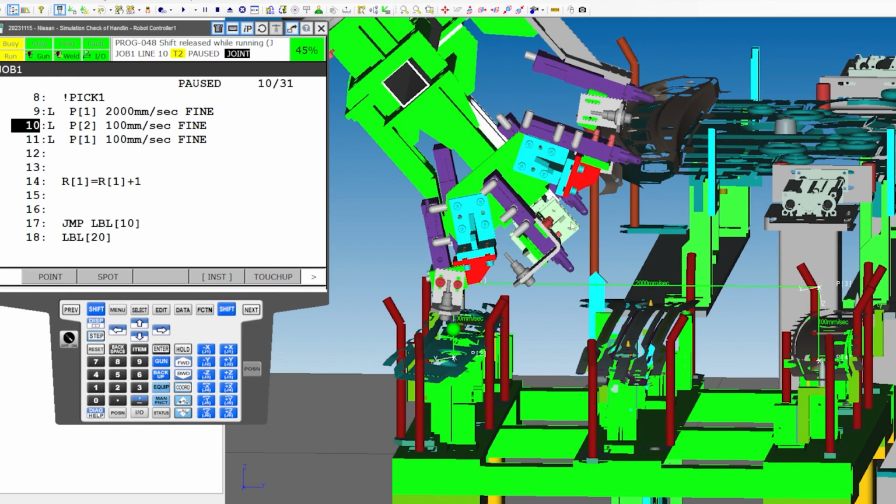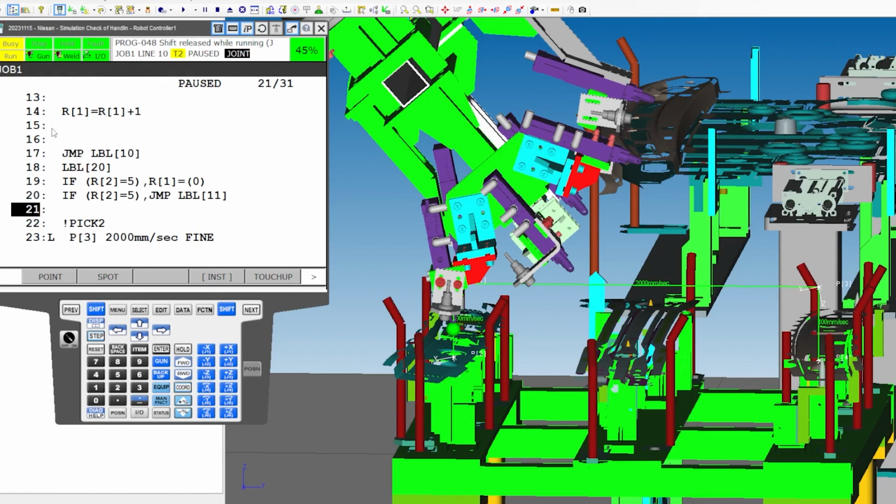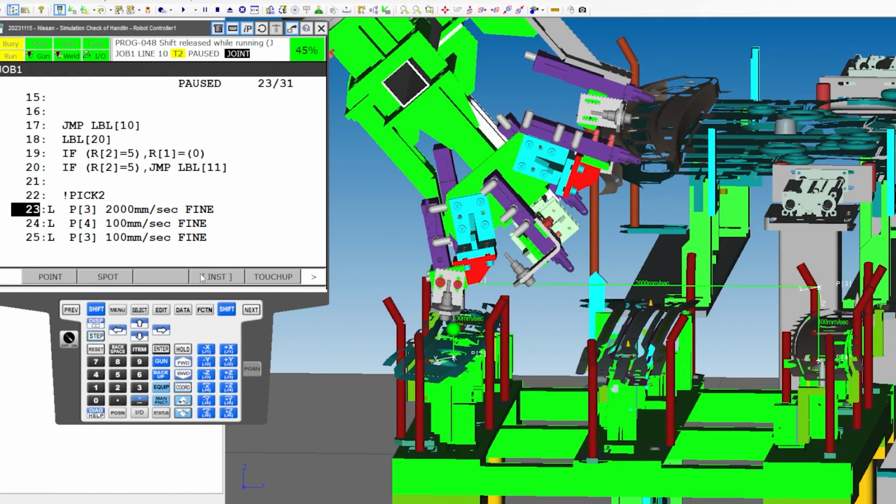But instead of doing all this under one tool, we changed the position of the tool. I'll just try to throw these in here real quick. I doubt it'll work appropriately. I think it's gonna throw a fit, if I'm not mistaken. So whenever we go to pick 2, I'm gonna set that to a different U tool. So first of all, shift coordinate to find out what tool we're currently in.